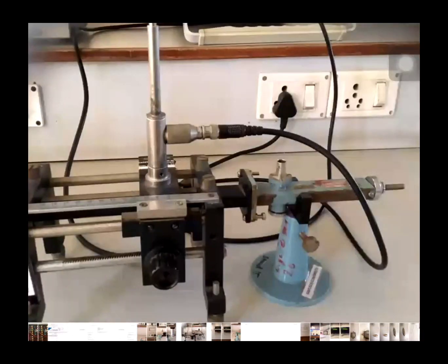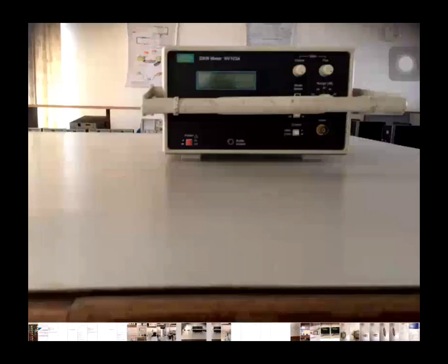And this is what we call a slotted line carriage or a detector. Here the waveguide is continuously connected, and the last gray thing which you see is once again the terminator. It will stop the propagation of the power. From the detector we give one cable to the CRO and the other cable to the VSWR meter.